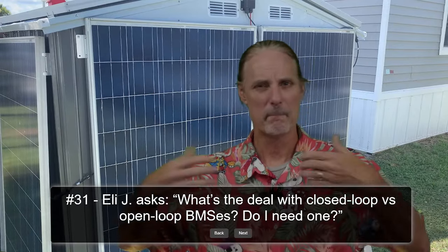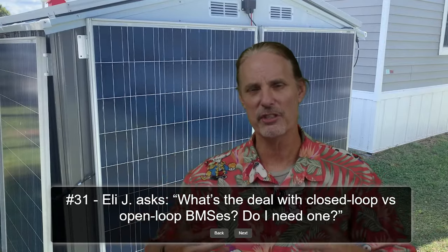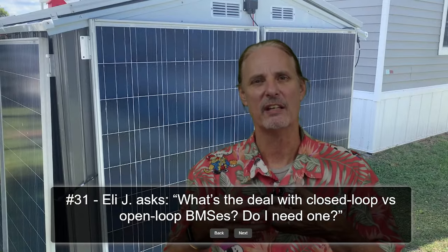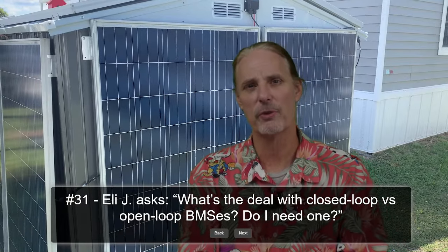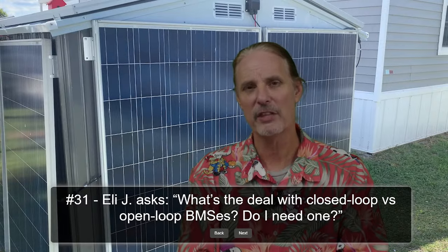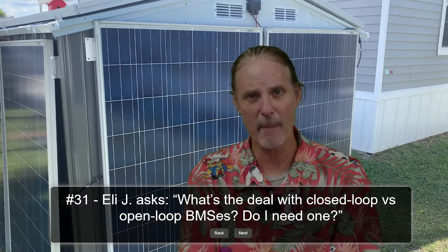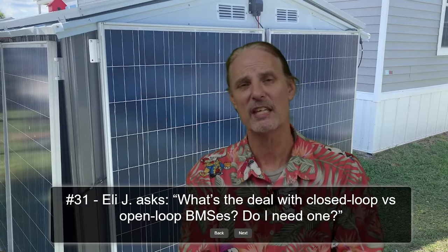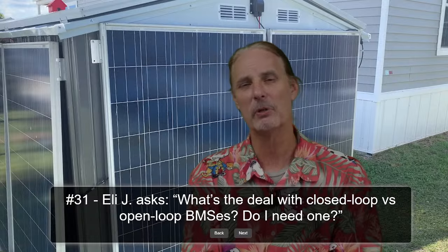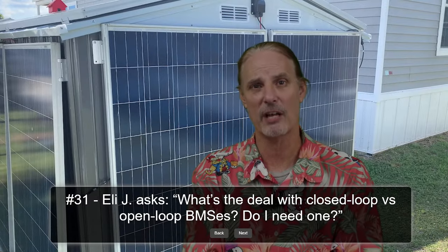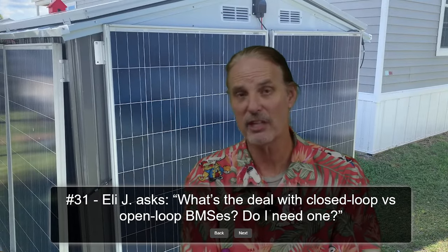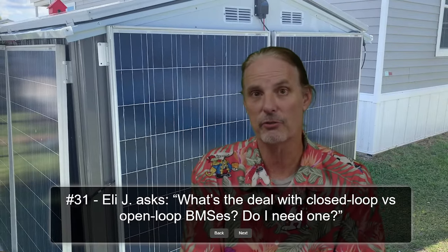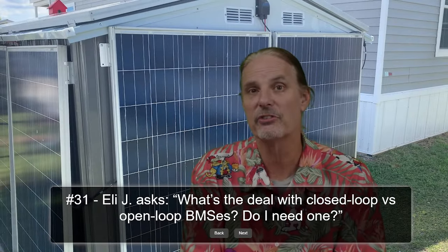Recently, with energy efficiencies and technology, BMSs and state of charge calculations with lithium iron phosphate became more complicated and they couldn't use the battery's voltage, so the manufacturers started building BMSs to protect these types of batteries. With the BMS came the built-in shunt, which therefore gave us the state of charge.